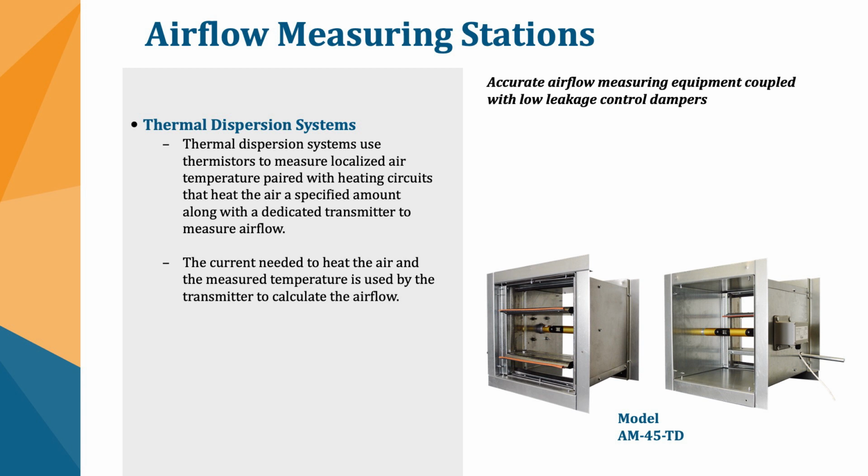Now, some of our pressure differential and damper combinations that we have right now use some pressure differential units with either a steel airfoil or an aluminum airfoil damper. We also have the same options available for the steel airfoil damper as well. So the naming convention pretty much mimics our control damper convention. So for the steel airfoil units, similar to the CD45, we use AM45 PD. So PD for pressure differential, AM for airflow measurement, and then 45 for the blade type.